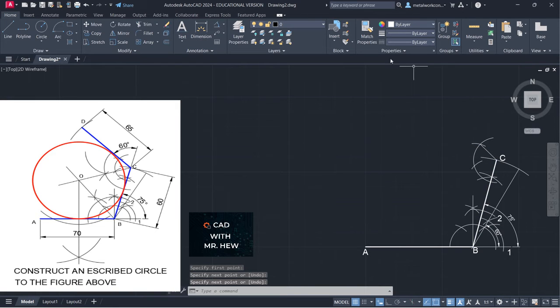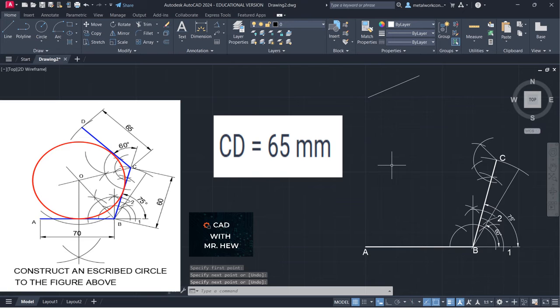Enter. What we're going to do, we're going to draw a construction line out here. Enter. And then when we type extend, EX shortcut, when we click on it, the line is extended here. Enter. So we can delete this construction line. All right.